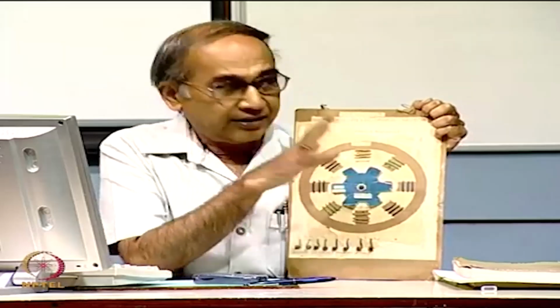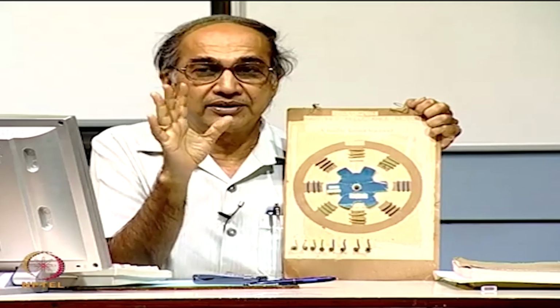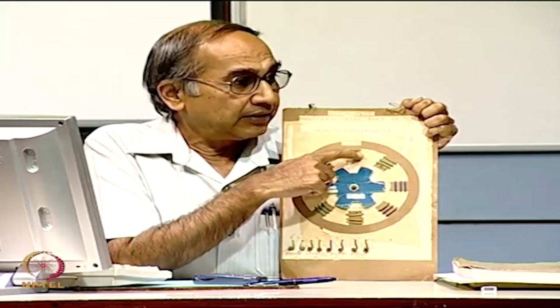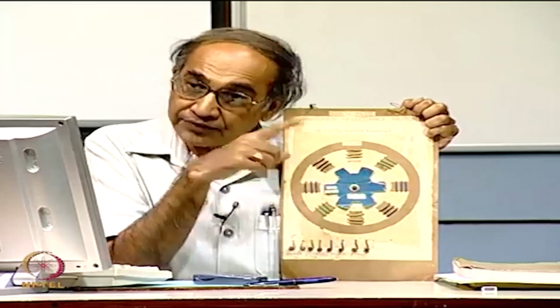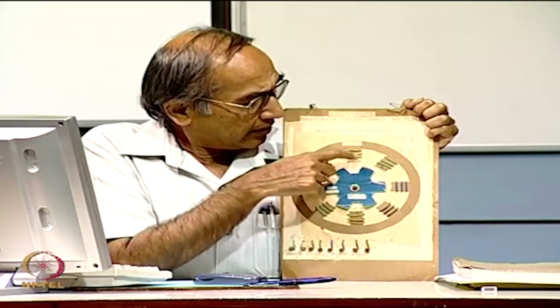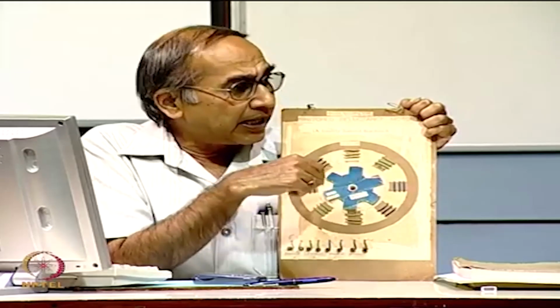Now, the other thing is that the inductance is a function of the rotor position. This is one thing you have learnt from now. Inductance of each of the coils is a function of rotor position. So, you can write L1, L2, L3, L4 as functions of theta, and all the inductances will not be the same at the same time, because when this is aligned, another may be unaligned.